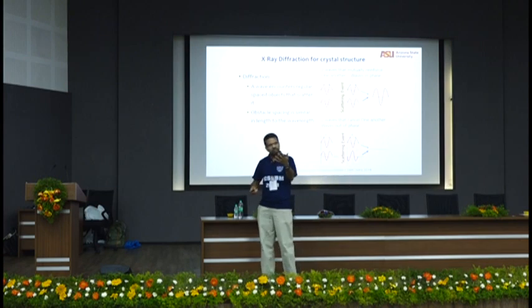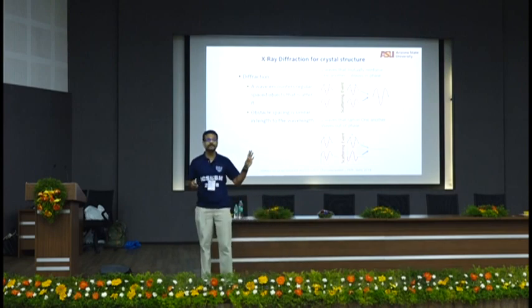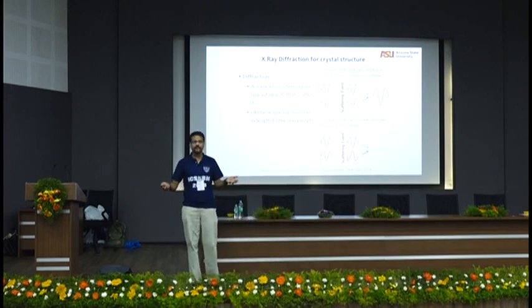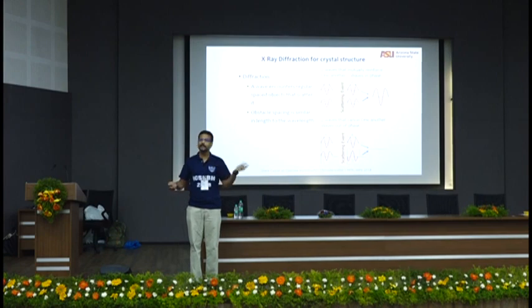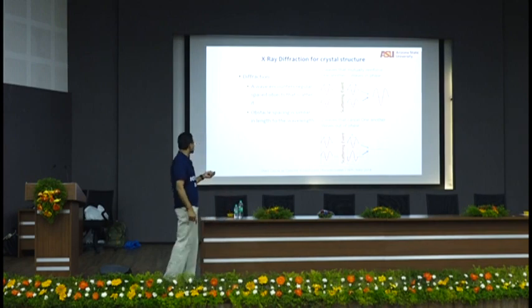Bone, more ordered, think of it as a crystal. It will constructively interfere. The amorphous part will destructively interfere. So through crystals you will see, through amorphous materials you don't see. That's why you get peaks in X-rays for crystals, and kind of flat or small bumps in amorphous materials. So that's a simple idea.